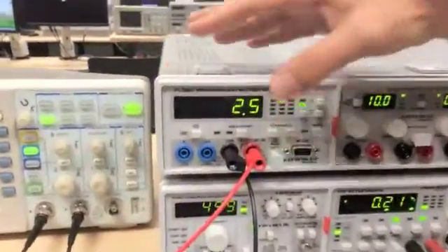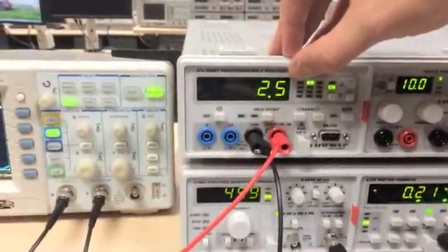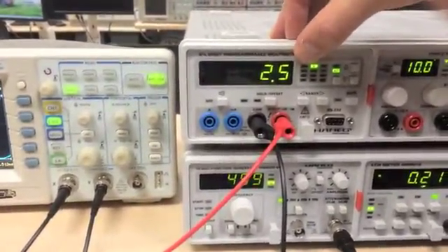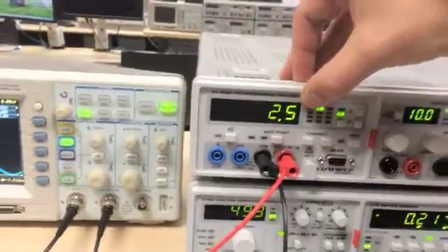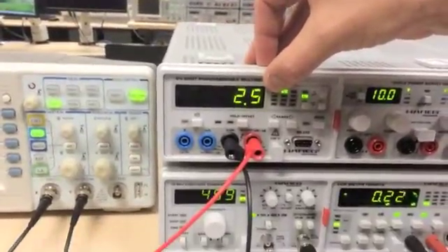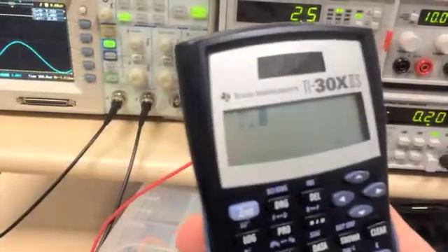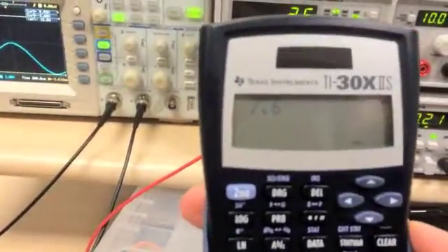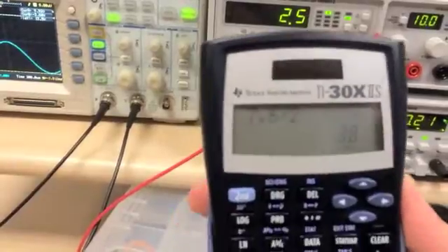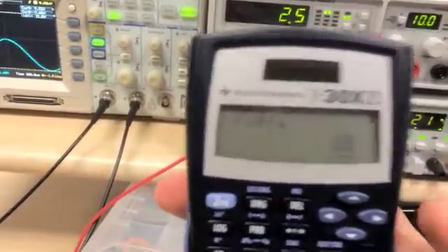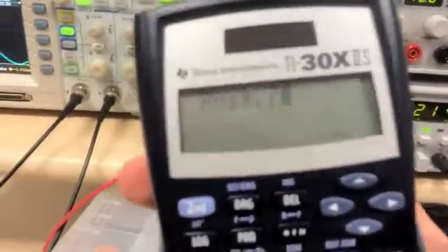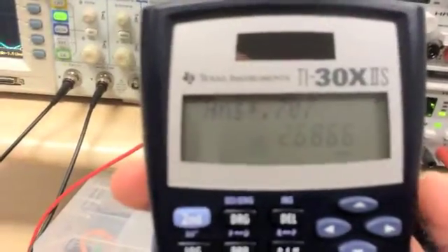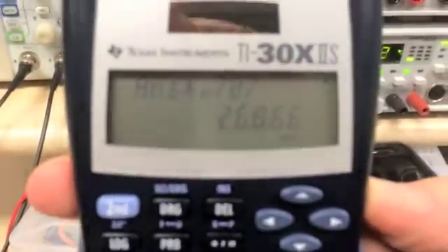The multimeter provides a measurement of the root mean square voltage, which across resistor 2 we're measuring as 2.5 volts root mean square. My 7.6 volts peak to peak divided by 2 gives my peak voltage, and then multiplying by 0.707 I have the root mean square measurement, which is close to the measured value. Since our measurement is old school, we expect small error.